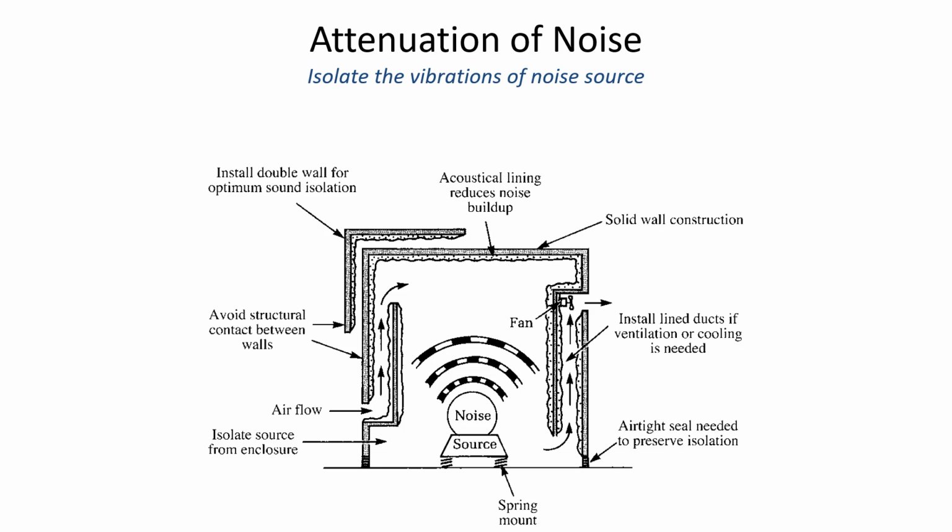So it's not practical to have complete enclosure, but what this is illustrating is a series of baffles, so that you could, in theory, have the air coming in, and maybe you're using a fan to induce the ventilation through the enclosure box. But the sound waves would have to take such an indirect route to get out of the box that they'd be largely absorbed and dissipated by the box and the acoustic lining on the inside of the box. So I've thought about building something like this for my little portable generator, and maybe one of these days I'll get around to it now that I've got a diagram here.